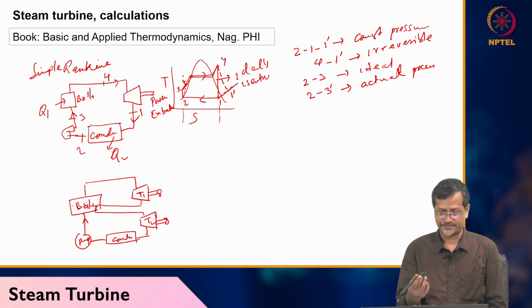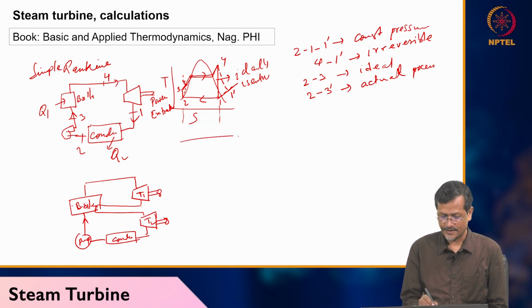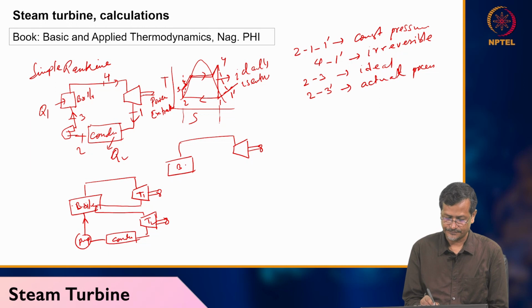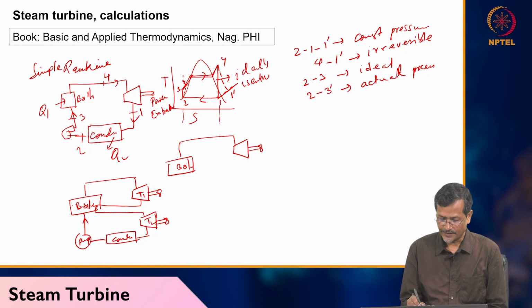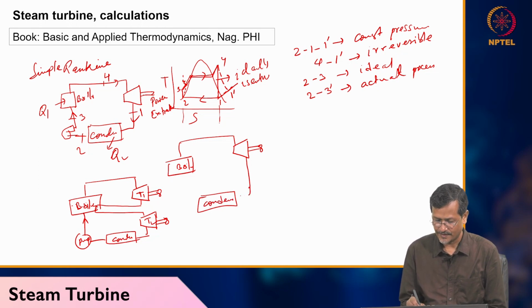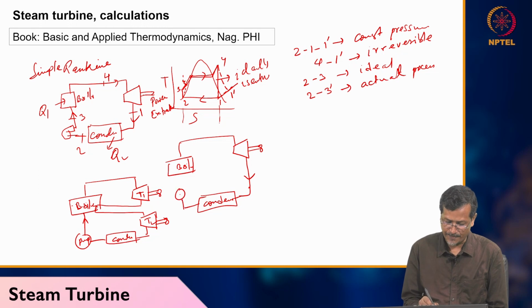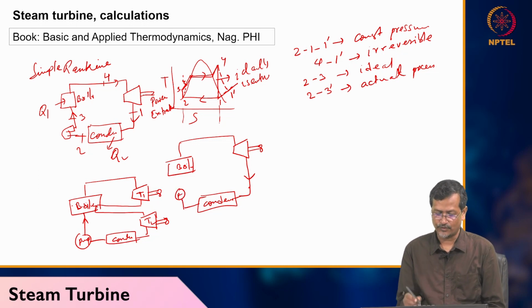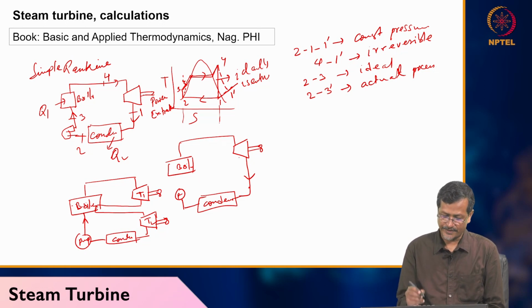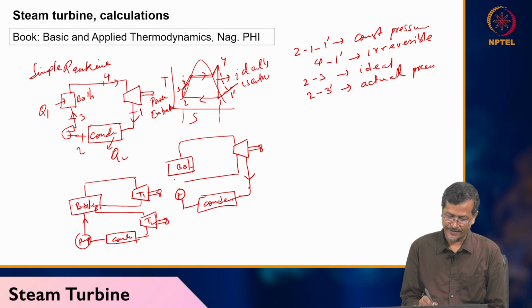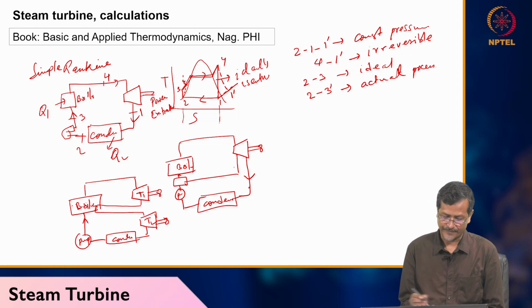Another is the regenerative system. In the regenerative system, you have a turbine, then you have a boiler. The turbine will have a condenser after it, then there will be a pump, then it will go to the boiler. After the pump, actually the water temperature is lower. Now what they do is take some amount of steam and give it here, then you are pumping to the boiler.